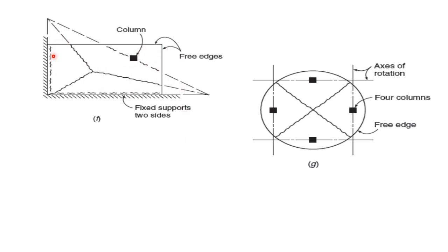This is also a simply supported case, the same as we have discussed. Here we have a circular slab supported on columns, with no support on the edges. We draw straight lines for all four columns, on all sides of the column, the lines of support, and each intersects at some point with another line of support.